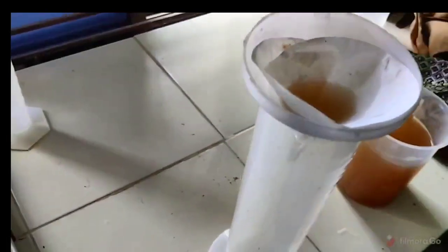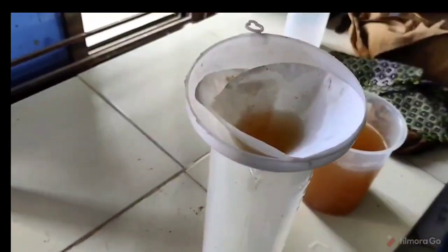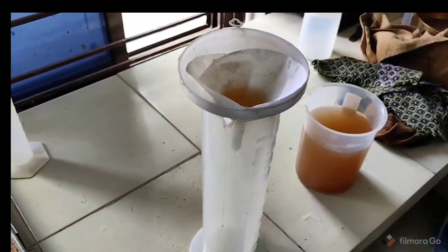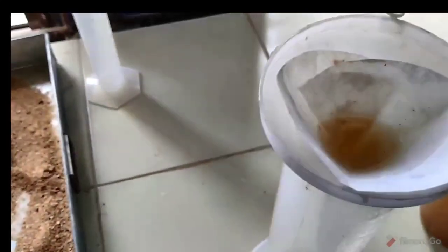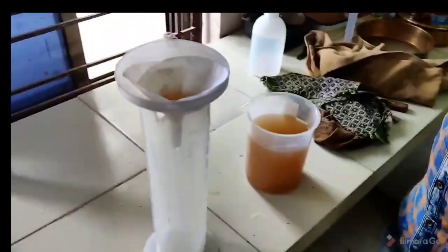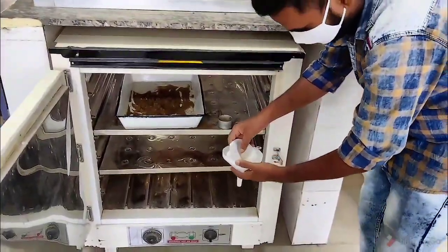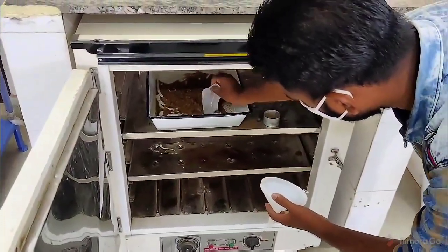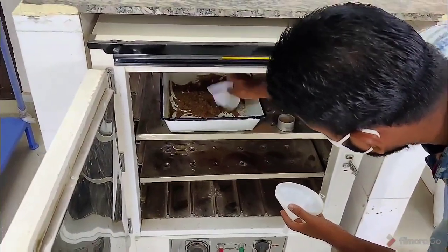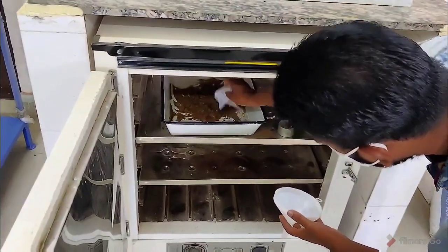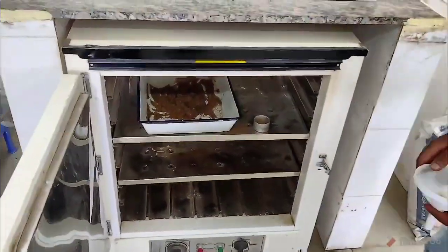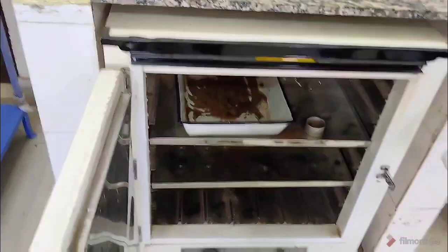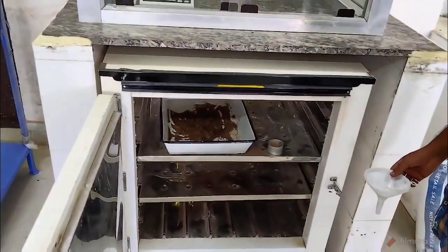You have to pour a small amount of water at a time, not all. You can see small particles which will be collected here. We will take it there. On the filter paper, we can see the amount of soil collected. We have to add it to the previously collected sand sample, and leave it for drying, and after 24 hours we have to weigh the total sample and note it down as D.